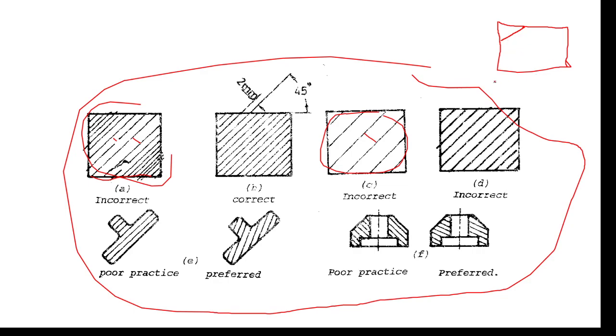In such a case, relative to the size of the surface, decrease the space value, so as to have more hatching lines. So what I mean is, the space value is selected relative to the size of the surface, which is the surface to be highlighted using hatching lines. Inventor, AutoCAD.